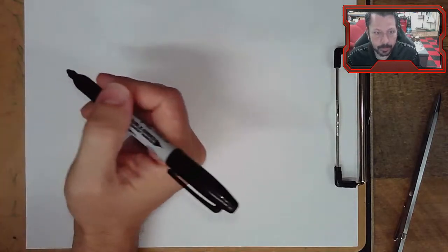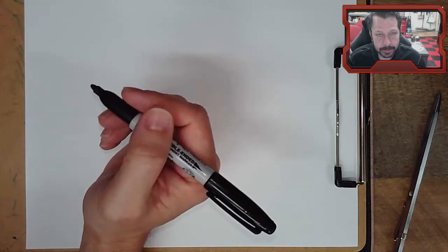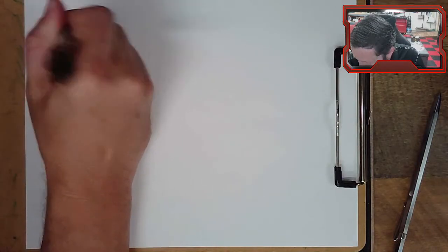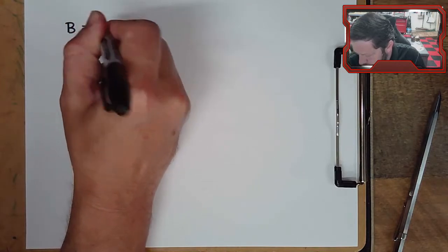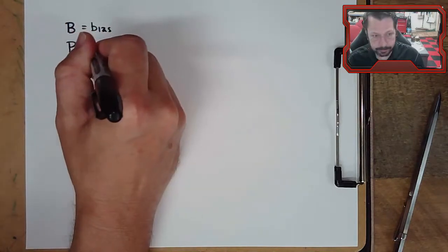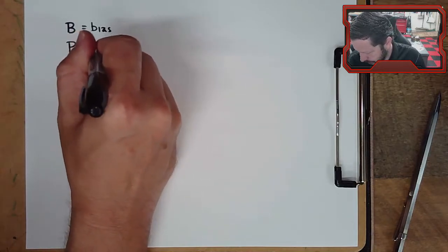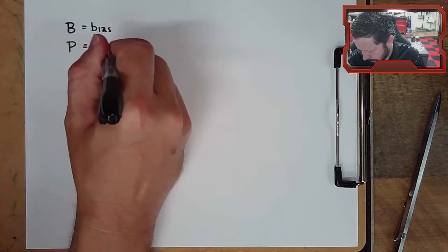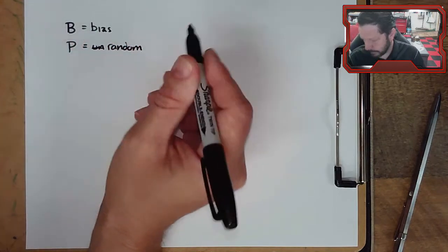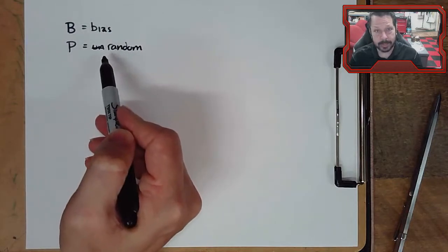And then there's all the random stuff that happens, like you take the measurement 3 or 4 times and you get 3 or 4 different numbers. So we have to combine these. If we took a single measurement, then what we could say is that the random uncertainty, remember, oh, I forgot this. We called B the bias error, and we called P the uncertainty, or random, we called it random, let's call it that. And so this was the systematic and this was the random error.